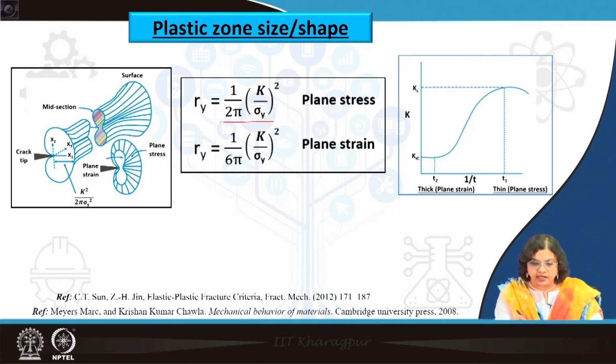On the other hand, at the interior part, particularly in the middle part, the plane strain condition generates, which essentially means a triaxial condition of stress and biaxial strain. So, overall the strain that is generated is being constrained, and the amount of strain generated is 1/3 of that generated under plane stress condition.